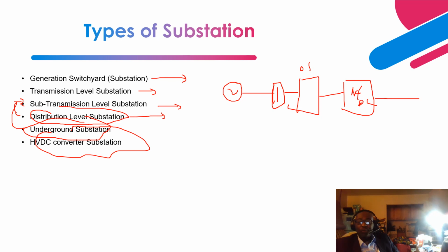Then it gets transmitted through a DC subsea cable until it gets onshore. Then it gets inverted from DC to AC. So here you have an onshore substation that is integrated to this converter. Similarly, for your offshore, you have a substation that is integrated to the offshore converter.